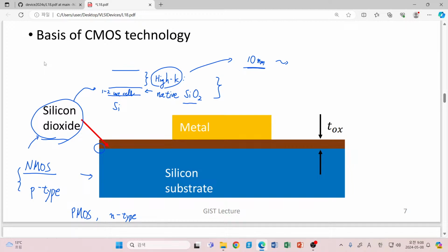The typical value of this p-type dopant in previous planar MOSFET technology was typically like 10 to the 17. This is a relatively low value, and corresponding to 10 to the 18, yes, this is a relatively high value. But we never achieve higher values like 10 to the 19 or something like that. This is prohibited because it makes our substrate too conductive.